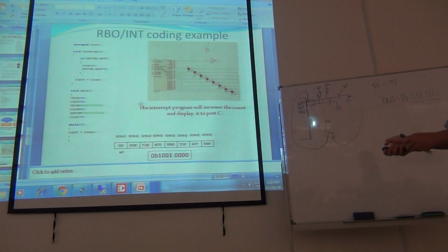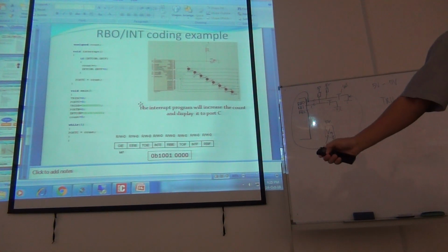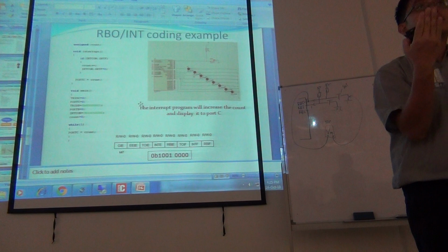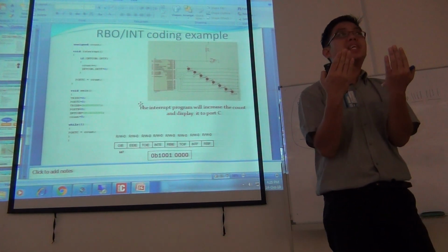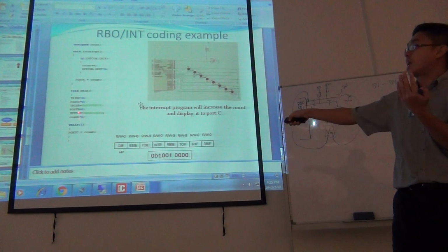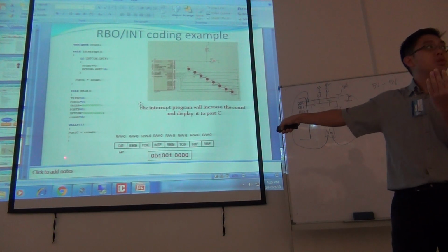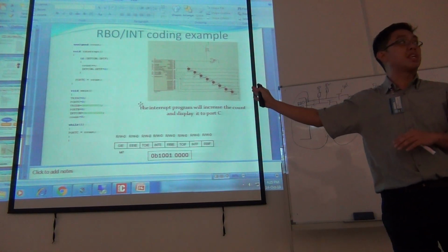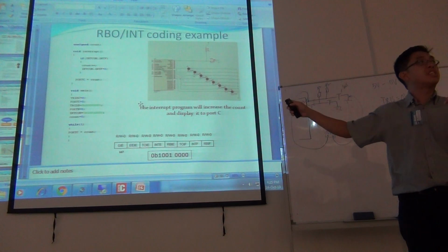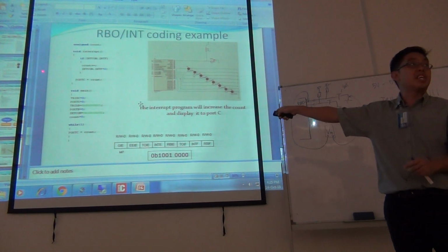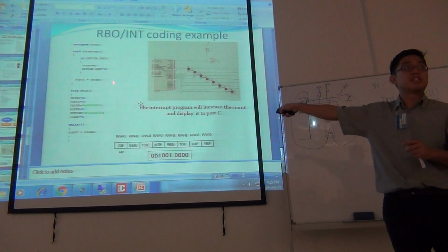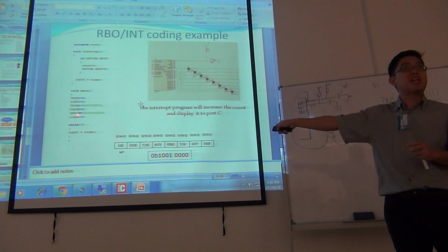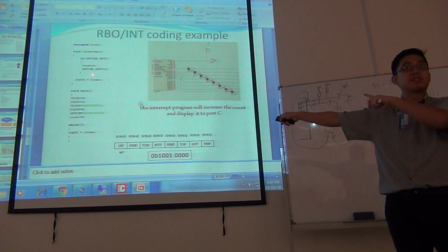So for the interrupt, now you can compare the difference from the switch just now, side by side. With the switch, the programming is basically inside the main loop. Whereas in this interrupt function, we also use RB0 as the external input. The thing is, for the interrupt, it will have this void interrupt function. No matter what, for interrupt, it must have this void interrupt function.